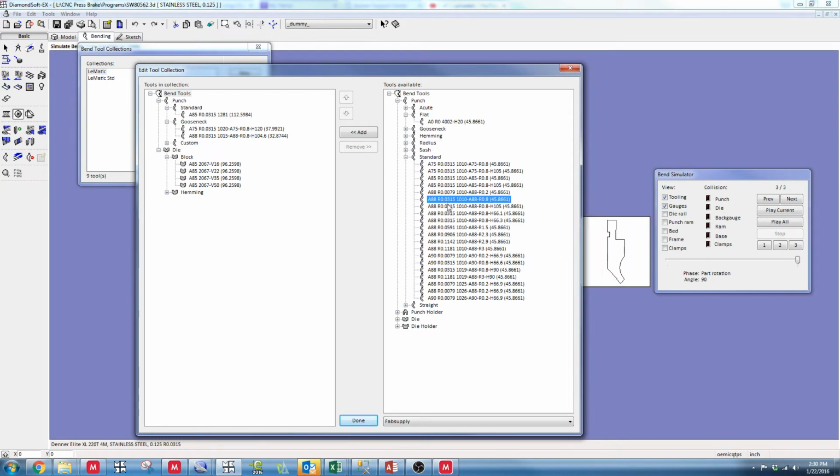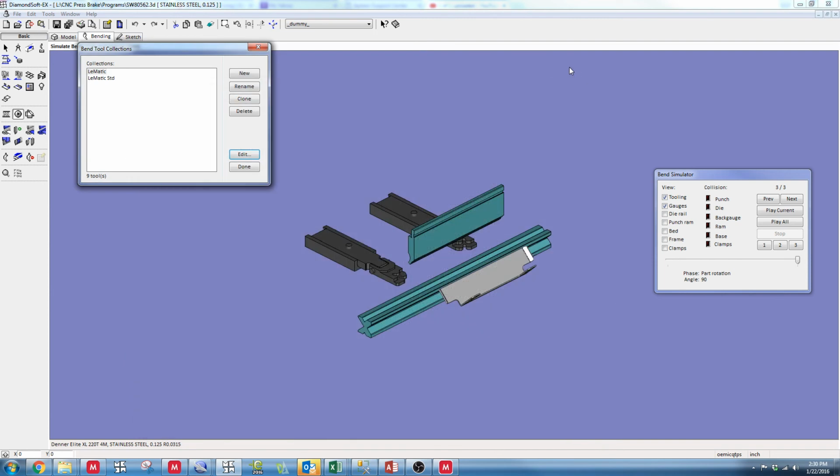This is really used if I get a situation where I have a part that we're trying to bend. The idea is that when you hit the auto sequence, we can choose this whole database from all suppliers, or one supplier, and let the system generate the best tool to bend that part. It may not be something we have, but with this we can program it and figure out what we need to buy. That's where everything resides in terms of being able to bend something or not. It's really a tool-driven system, and that's where it starts.